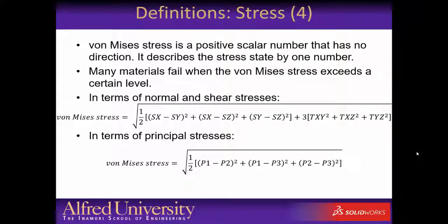Now that we've noted that stress at a given point within an elastic body is a tensor quantity, we must ask ourselves, if we wish to understand how a material fails, which is normally denoted by a certain threshold strength value, which is a scalar value. It has no components associated with it. There might be some ambiguity in trying to assign which stress value to compare against a strength.